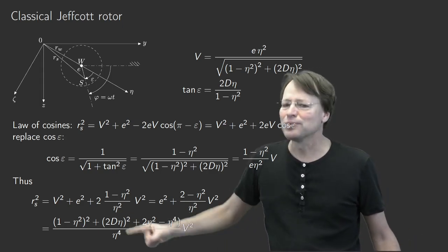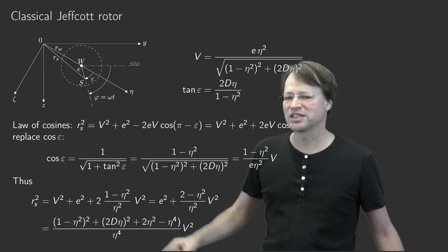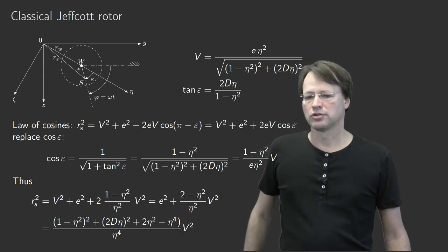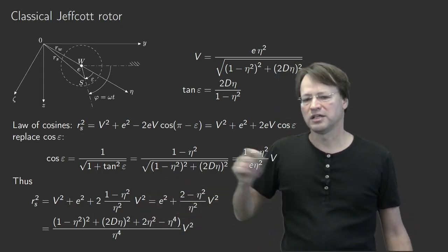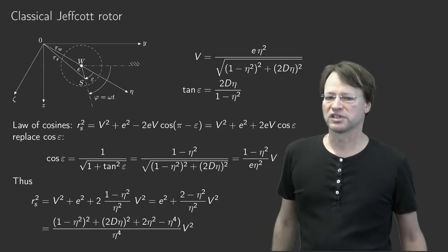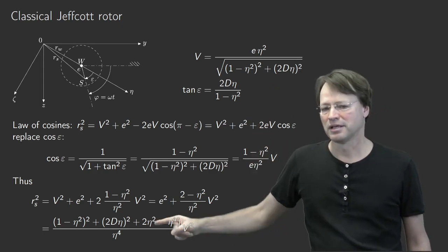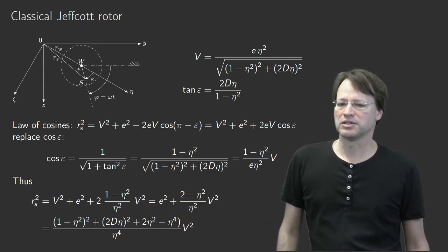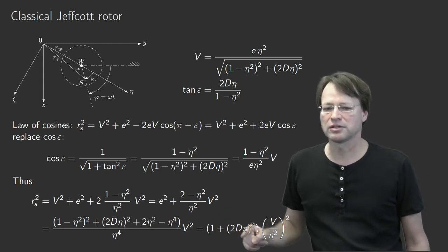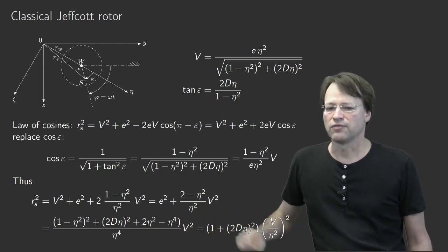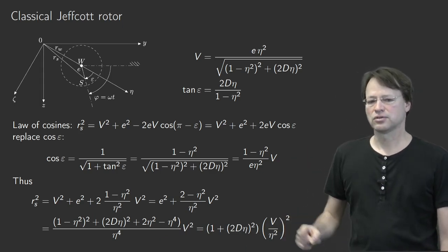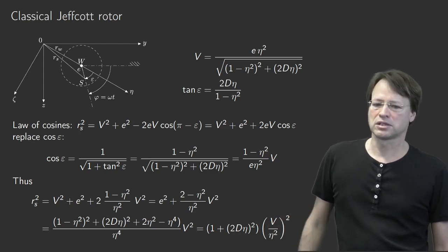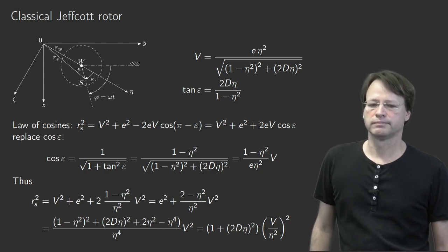It's nice, right? We lose nearly all the terms in the numerator here, except for the first one, if we apply the binomial formula, 1. And the middle term, 2 d eta, which is the only term that contains the damping, by the way. And of course, in v, the damping is also hidden, but in that ratio, that's the only term where d is explicitly present. So we get just 1 plus 2 d eta squared. The eta in 4th power moves now to v, so v divided by eta squared and then squared, then we have eta in 4th power, and this is the solution we obtain here.